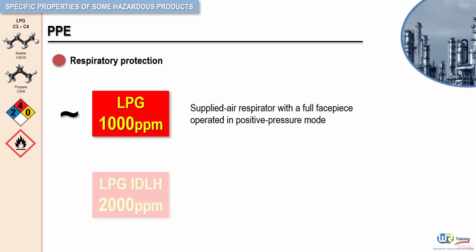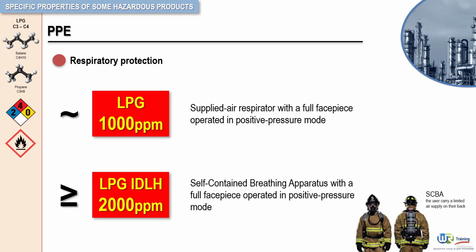Exposure to 2000 ppm is immediately dangerous to life and health. If the possibility of exposure above 2000 ppm exists, then use an approved self-contained breathing apparatus with a full face piece operated in a positive pressure mode and equipped with an emergency escape air cylinder.